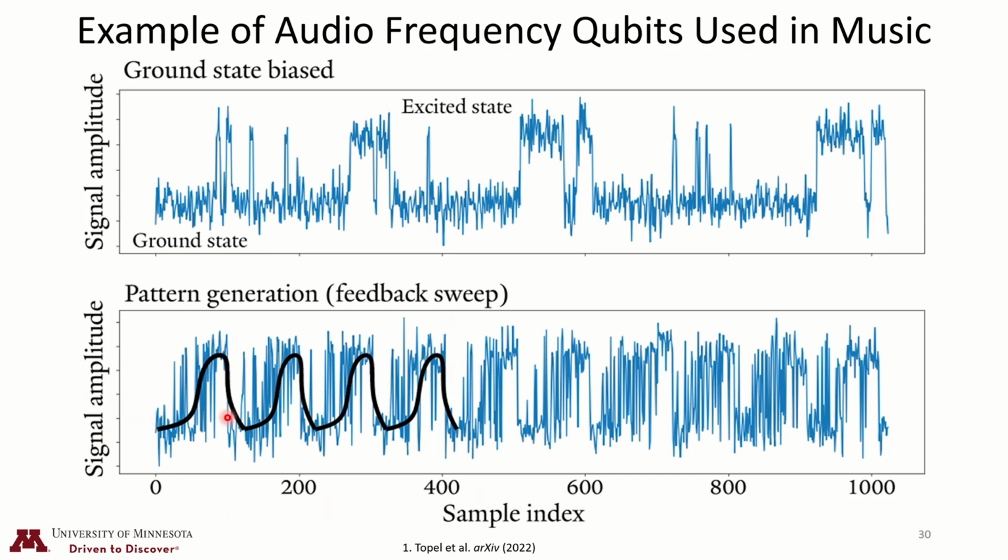And then you can use pattern generation. You can use computer code to create these waveforms. And then if the waveforms are moving too quickly, you can diminish the frequency into the audio range. So audio range frequency is anywhere from a few hertz all the way up to about 20 kilohertz, which is audible for human beings. And if you were talking about animals, maybe like a dog, the audio frequency for them might be much higher, maybe 40 kilohertz or more.